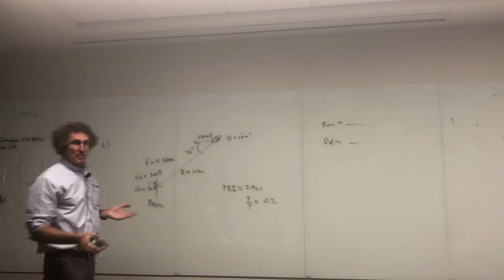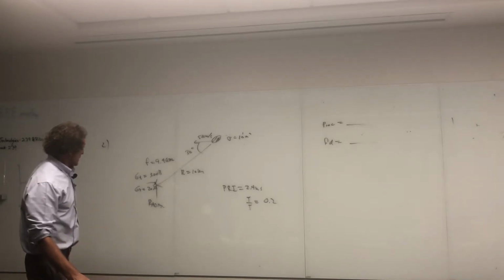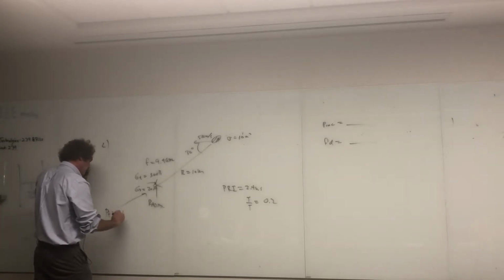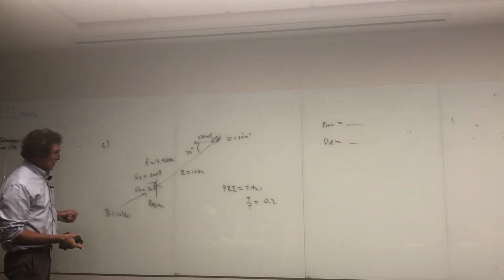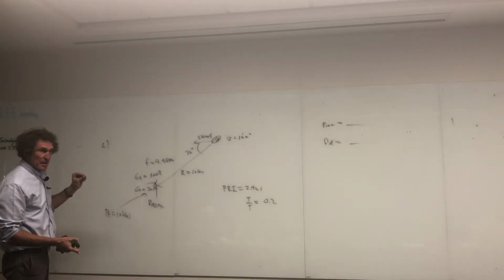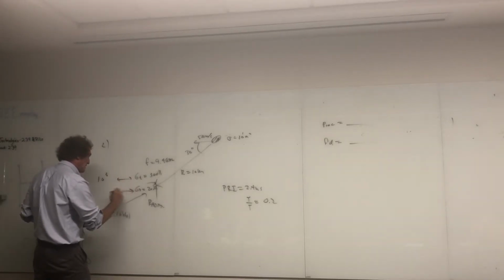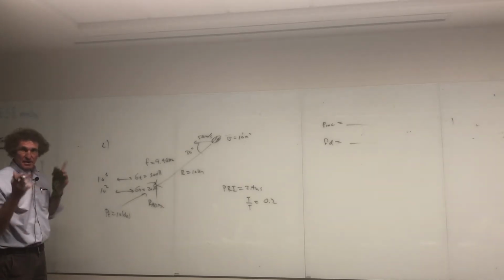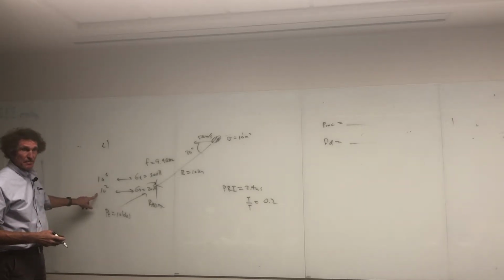You didn't write it down, but it's a 10 kilowatt radar. Power transmitted is 10 kW. For the first part, it's an absolutely straight plug and chug thing. A gain of 30 dB is 1,000, or 10 to the third. A gain of 20 dB is 10 squared in terms of the linear values. Just make sure you don't make the mistake that people often make of just sticking in 30 or 20. Those are in dB, and this is the linear gain.